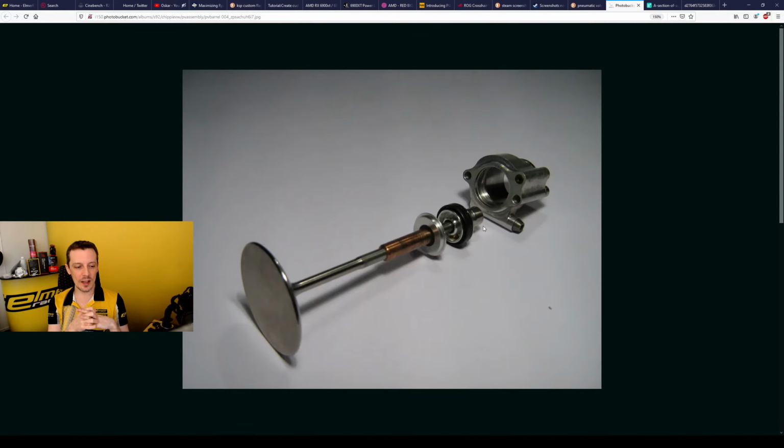Typically you will see some kind of small helper spring, so when you shut down the engine, the valves won't glide open over time due to the force of gravity. But I'm not sure about F1 engines. Do the current ones even use pneumatic valve springs? I mean, they are really low RPM, so I'm not really sure if they do that or not.